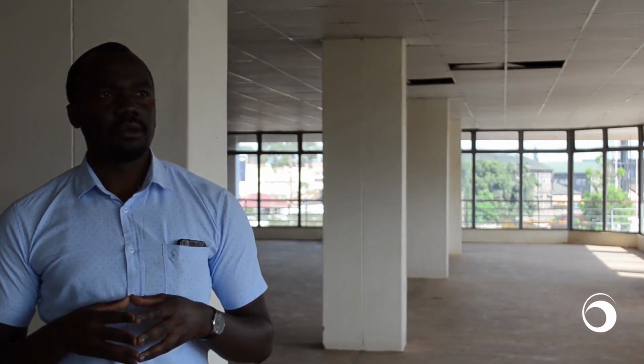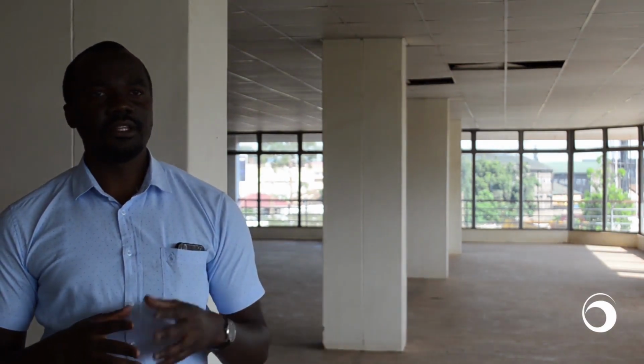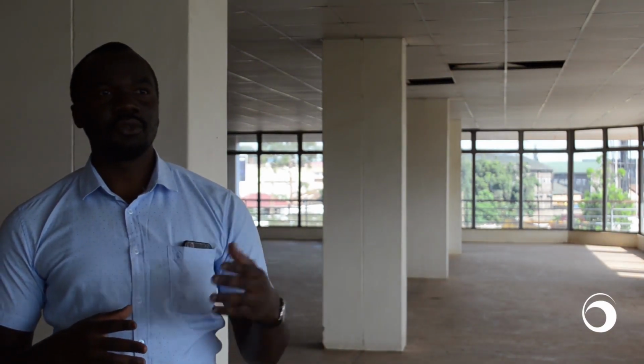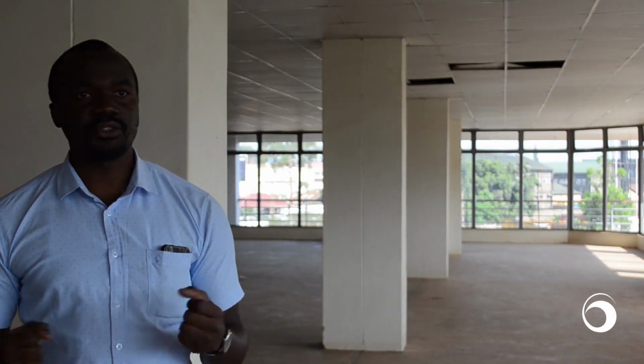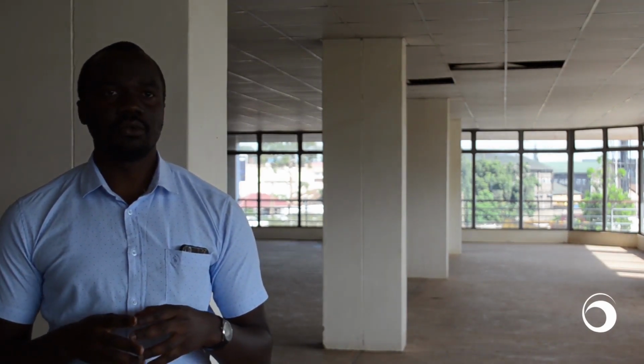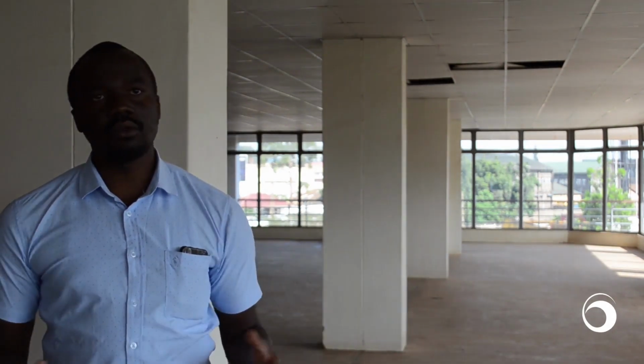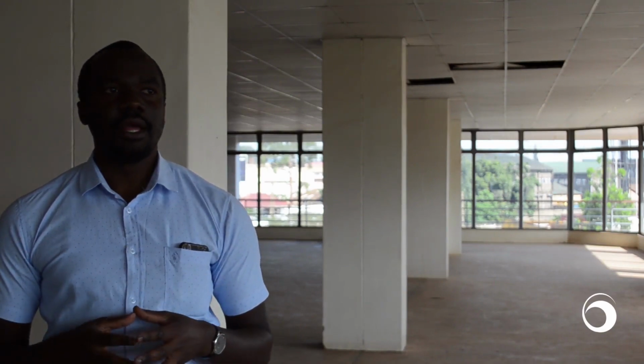The case in point is if you have a timber clad facade and it's not treated for weather, it's definitely going to start rotting when exposed to continuous rain and sun and heat. Expansion and contraction will make it rot faster than it's supposed to. So in such a situation, you're supposed to prepare the timber for those conditions. If not prepared, then it will fail. And the same goes for all other materials, even a simple item like a brick. A common item like a brick, if it's going to be exposed to weather, then it needs to be prepared for the weather.